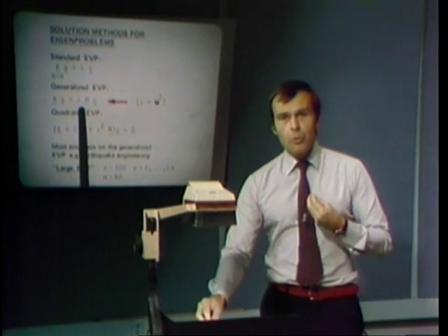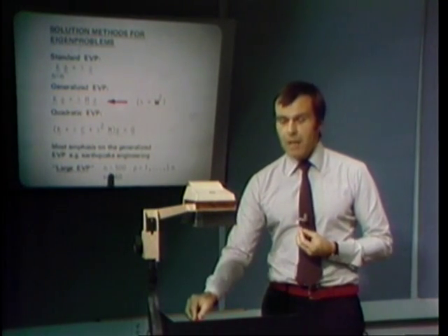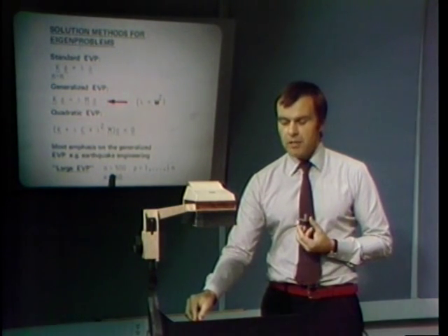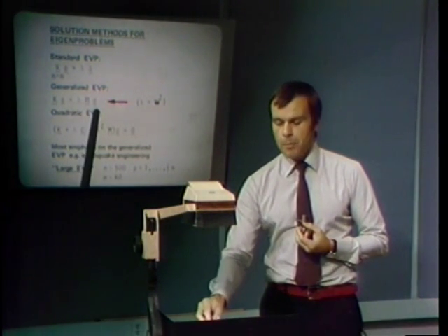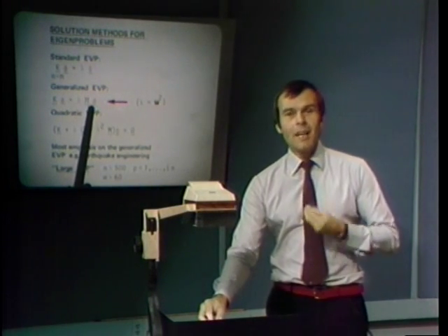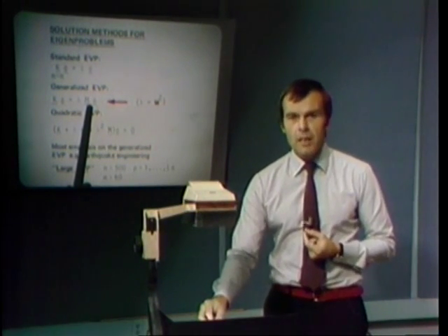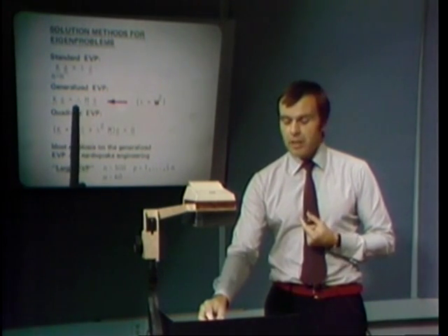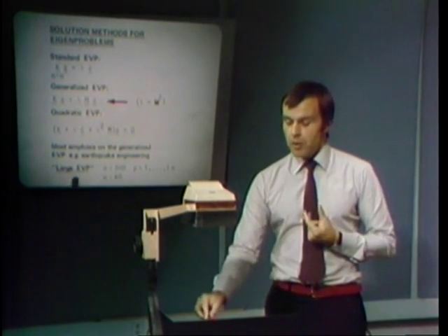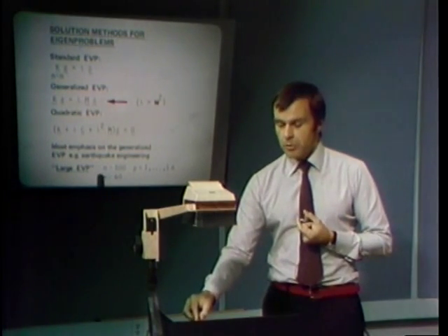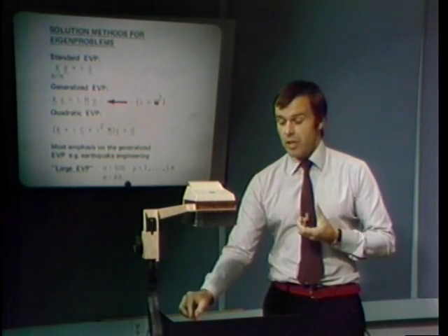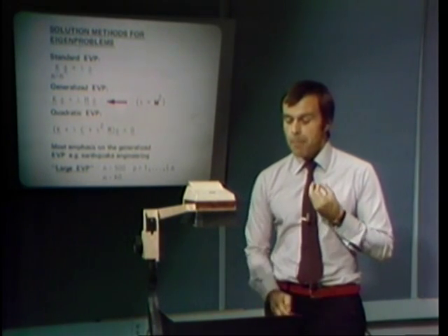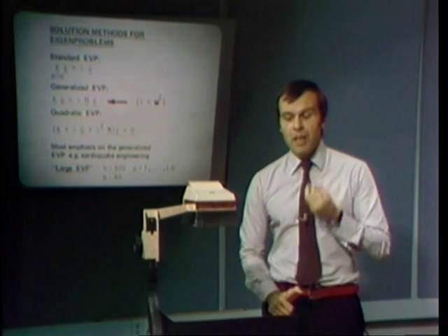When we have a small eigenvalue problem, in other words, n being small, say 50 or 100, there are a large number of different techniques that can be used to solve this eigenvalue problem, and it really does not make that much difference which technique you're using. The cost can still be quite significant, but certainly when we're talking about very large eigenproblems, n being even larger than, say, 1,000 or 2,000, then it is of utmost concern to select a technique that is very effective.